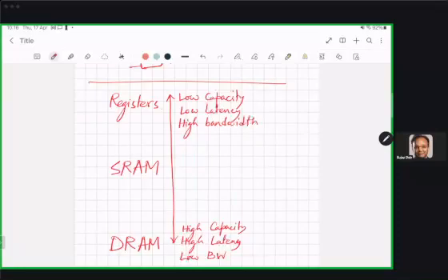So that means as a hardware designer, you have to ensure that you give that much memory, because if the program is trying to access some memory location which you have not defined, then the program will crash, right? So now I need to provide this much high capacity of memory. Even for a 32-bit address space, I need 4 GB memory to be provided. So that's why we will use the high capacity DRAM to provide that. This is called main memory, right?